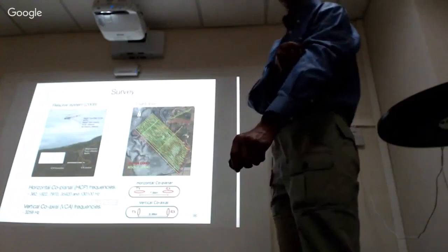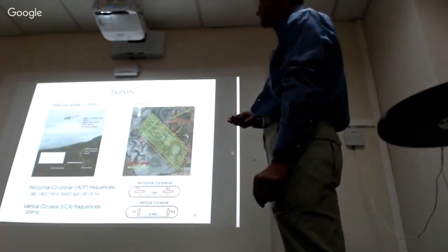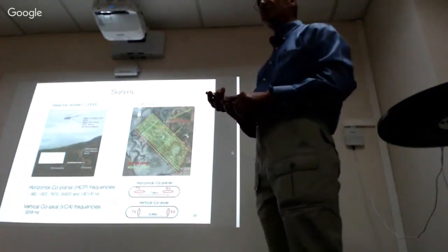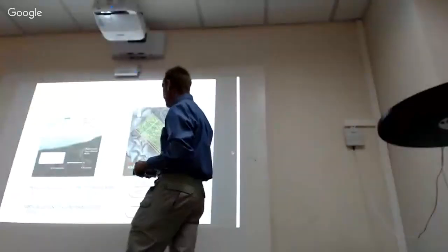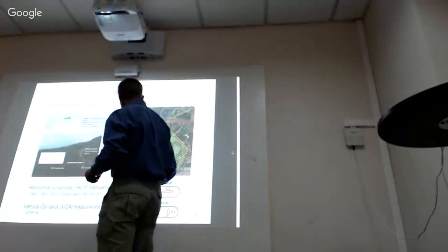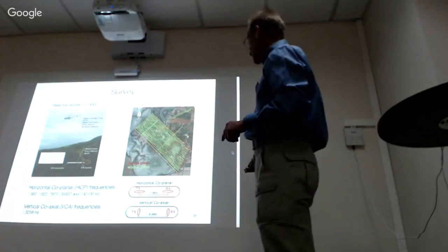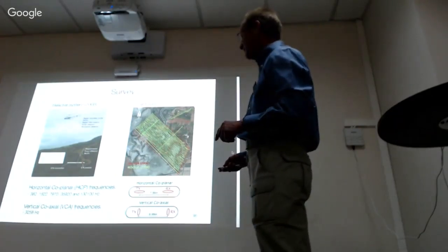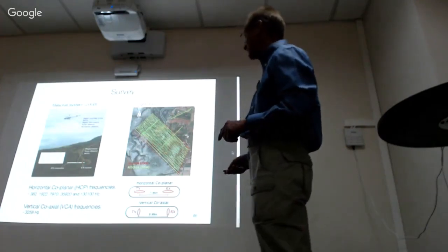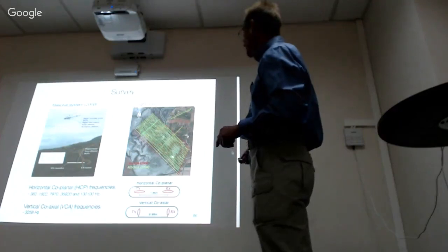So the survey, I'm going to do a time domain EM survey and also a frequency domain. So they did the SkyTEM, which we analyzed, but they also did this frequency domain system. Here we are. Here's the bird, and it's got coplanar coils. So here's transmitter and receiver, about 8 meters apart, and there are 4 frequencies from 400 to 130,000 hertz. And the flight lines are given here in green.